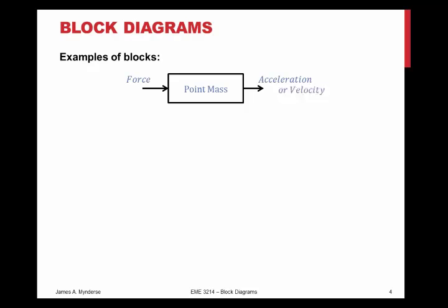But we could also say force goes in and velocity comes out. Well, velocity coming out, that's going to be an integral, which in Laplace is really easy. Or position comes out. Again, it's a double integral, and in Laplace that's really easy. So that's going to end up still just as a function of s. If you don't know what function of s I'm thinking of, review your Laplace notes.